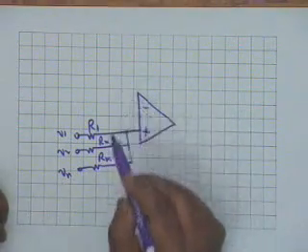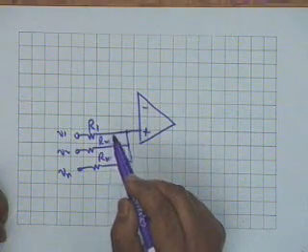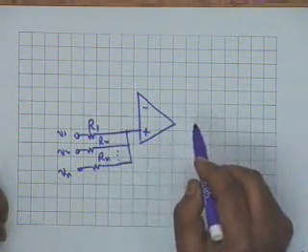Can I, for example, ground this? Oh, I cannot do that, because an operational amplifier, because of the high gain, can never be left open circuited, except in very special situations. We cannot leave it in an open loop. We will clarify this later in great detail: a high gain amplifier should always be operated with feedback, and feedback should be negative feedback.